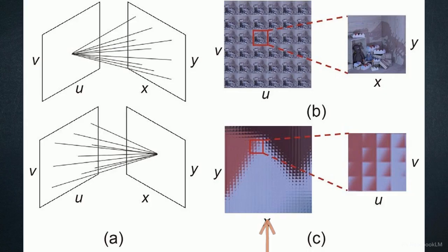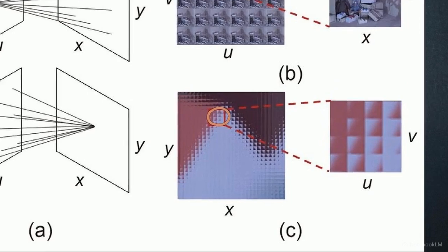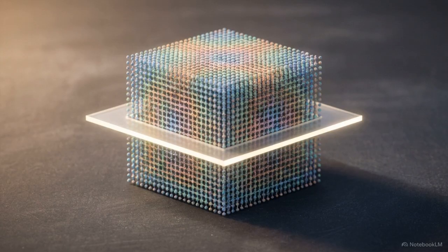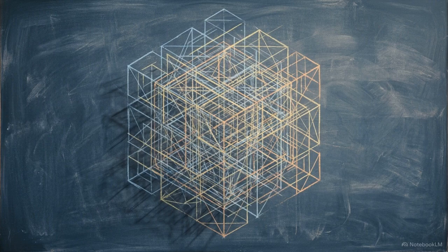On a physical camera sensor, this tensor manifests as macropixel images, or MACP. A MACP aggregates spatial and angular data into a dense pixel block mosaic, capturing high volumes of angular data per spatial coordinate. This creates a highly machine-readable but visually unintuitive structure. This intact 4D tensor contains the geometric data needed to extract sub-pixel depth, but it must be mathematically sliced to be processed efficiently. Processing a raw four-dimensional array natively is too computationally expensive for dense depth mapping.